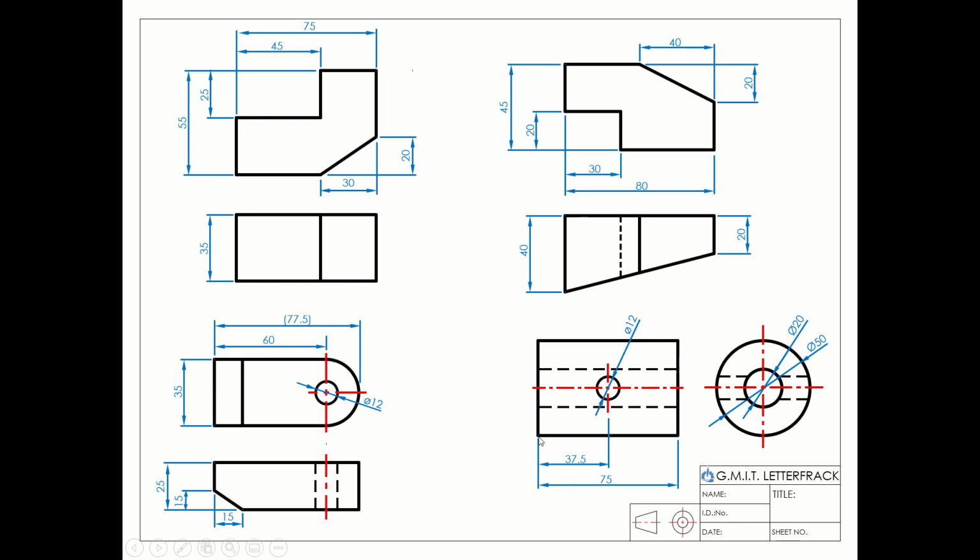You can see I'm just giving my overall length there, that's 75, and I've given a dimension here for the hole located like that. So if it was really important that that was 35, and this could be a bit longer, if that wasn't the important dimension, I put my dimension at that. If it's really important that that hole is located in the dead center of the piece, what I would do is put in my two little strikes like that to indicate that it should be centered on it.